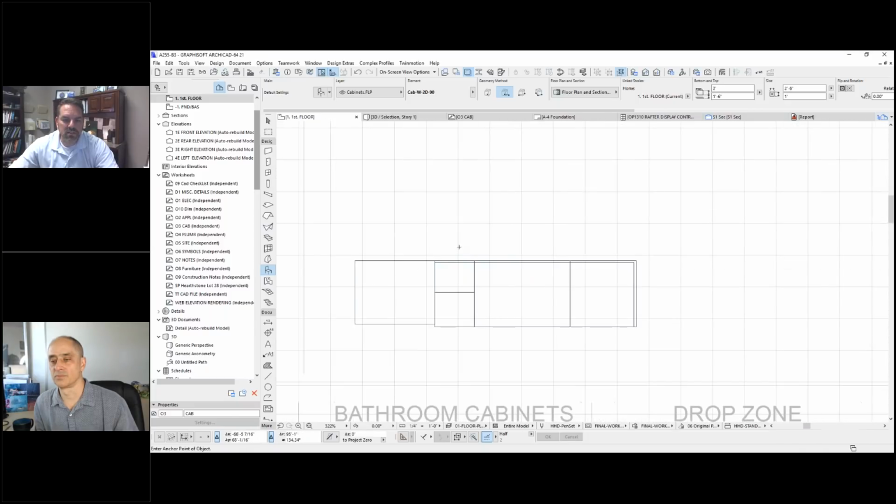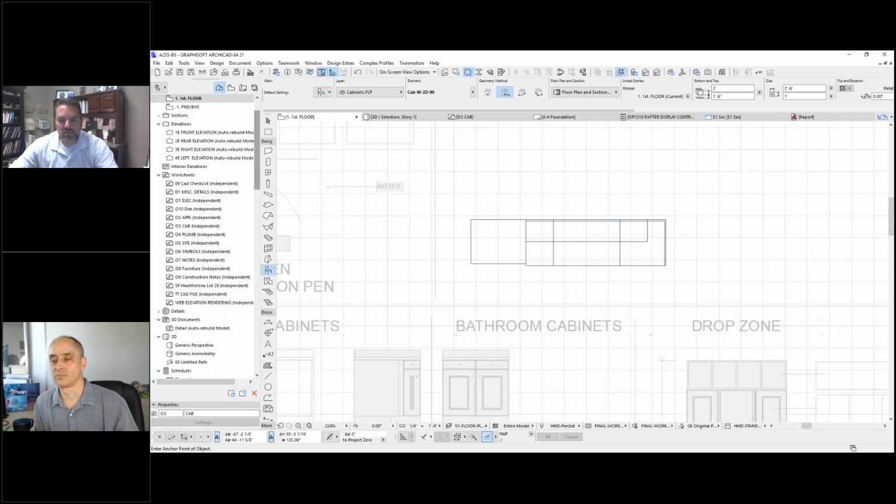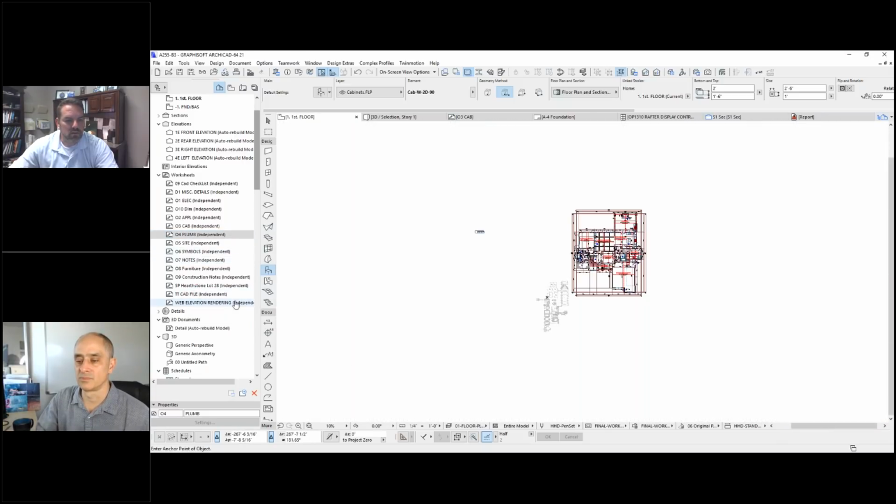And then once you place these, we can easily go in and select and change the length to 3 foot here, and then if I want to mirror, to close that cabinet out. Now that I've got this base cabinet where I would probably put a sink here and a double oven here, I can right-click and show trace reference of my plumbing. Then you can get your plumbing over.